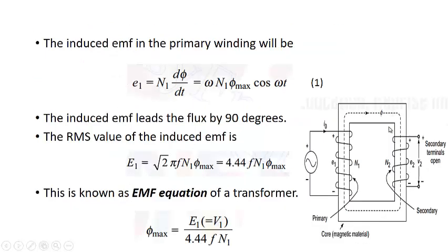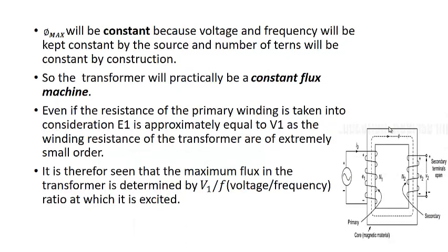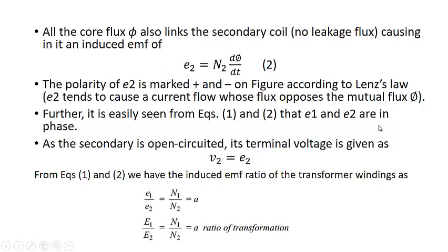So I have explained this in the first slide itself, how to get the plus and minus. We just have to first select the direction of the flux which will be opposed to the main flux, and then as per that we will point the thumb in the direction of the opposing flux, and the curling fingers will determine the current. And the point at which the current enters the winding, we mark that point to be positive, sorry, negative.